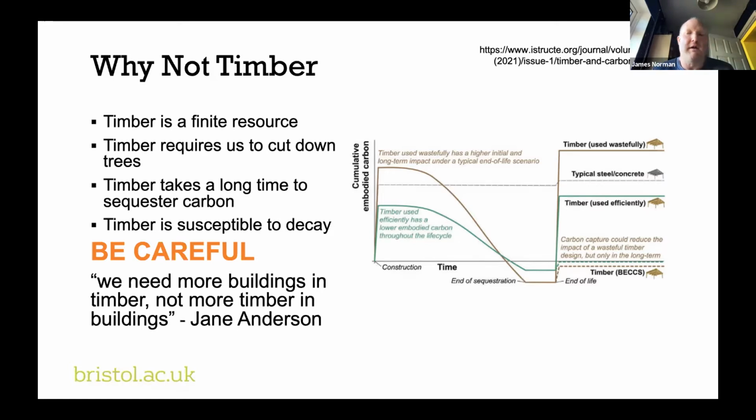And the reason that concrete is so damaging in terms of CO2 is because, let's be honest, it's amazing and therefore it's cheap and therefore we use loads of it. So that's why 8% of global CO2 emissions are down to concrete, give or take. It's because it's an incredibly efficient, incredibly affordable material. Now, if we switch all of the concrete use in the world for timber use, I think we're creating a whole load of new problems for ourselves, which is why we have to start with building nothing and building less.